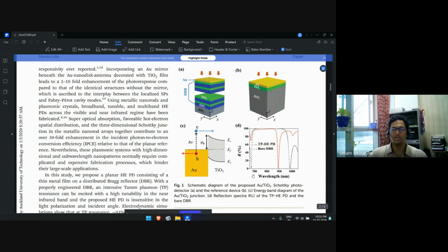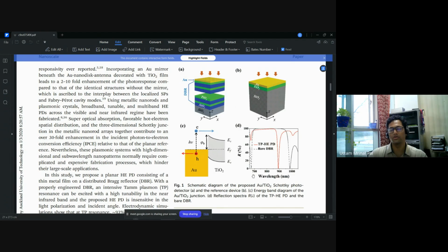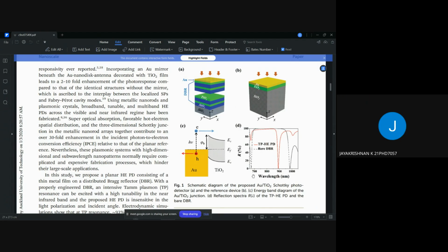You mention the thickness in TBC. Usually TBC is assigned for materials whose skin depth is almost equal to their physical thickness. If they are almost matching, then TBC is a good way. So instead of modeling the thin volumetric domain, you just model it as a boundary and apply TBC on top. See how it works. Okay, thank you.